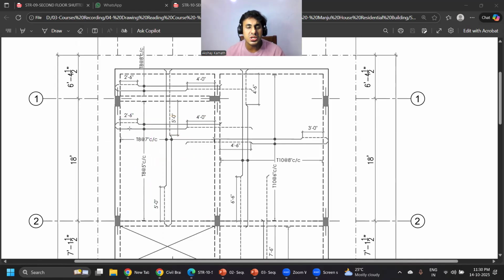Now coming to this particular drawing, we'll start the bar from here. Let us say I'll start the bar like this, and I'll give you a small crank. Crank means it's a bend. I'll bend it like this, and I'll take it to the top. Got it? Next bar, I'll take a bar from this direction now. After that, next bar, I'll start from here, give a crank this side, and take it continuously like this. Then again, I'm going to repeat the same thing. Next bar, I'll start from here, bring it up to a distance, give a small crank here and take it to the top. Then again, you can see the black color, right? So again, I'll start from here, give a small crank and take it to the top like this. This is how I'm going to place the bar.